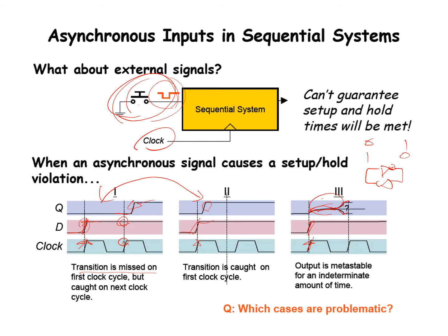So how do we avoid this kind of issue? We know that this kind of input signal is called an asynchronous signal, because we cannot determine the timing of when this signal changes with respect to the clock signal in our system. This is a very common problem for digital designers. So we have to reduce the failure probability. We'll see how we handle this kind of issue.